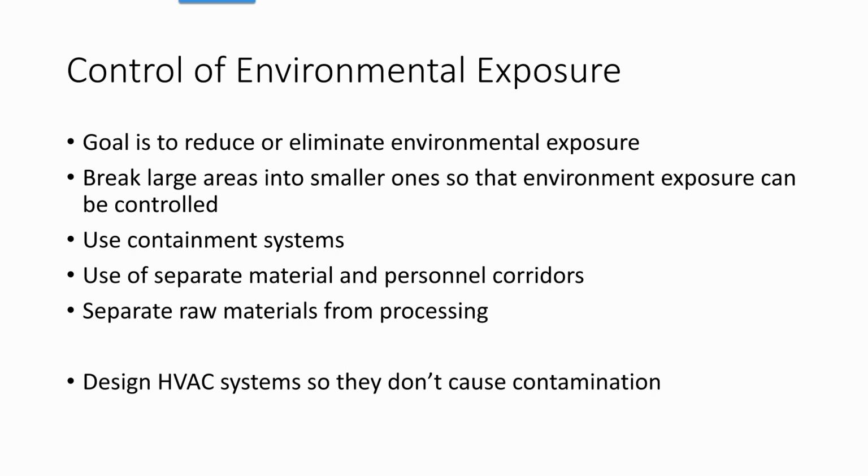And from an architectural perspective, that kind of goes back to what equipment is being used. But oftentimes, the architect can help out by just encouraging, hey, look, this is the cost it's going to take to make all these rooms a level 3 level of protection. It's going to cost you a lot. So let's look at maybe reducing the number of rooms that we have to really control and adding in some containment systems instead.